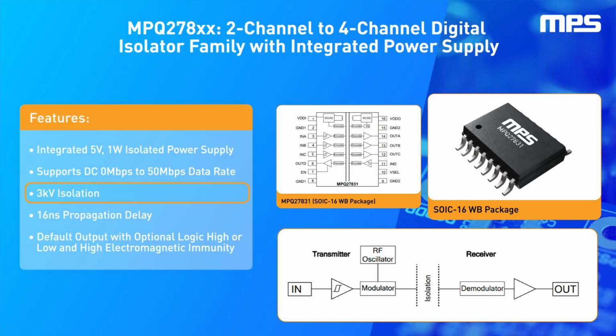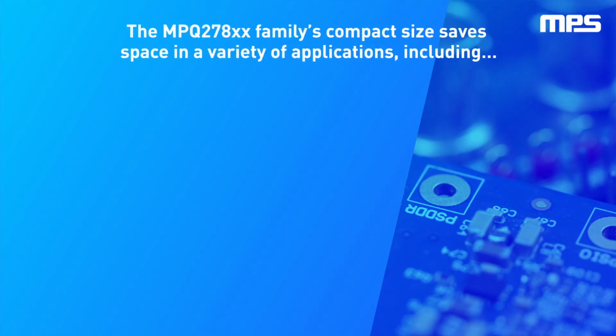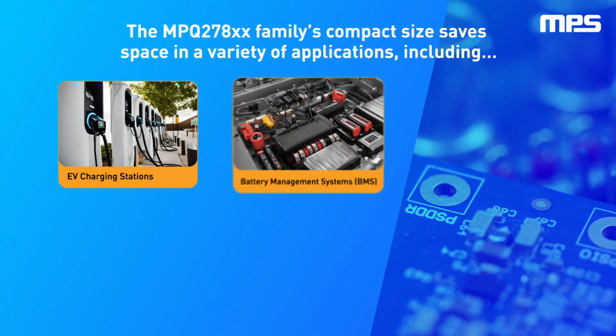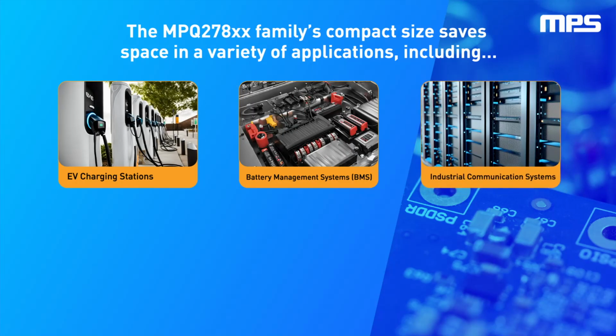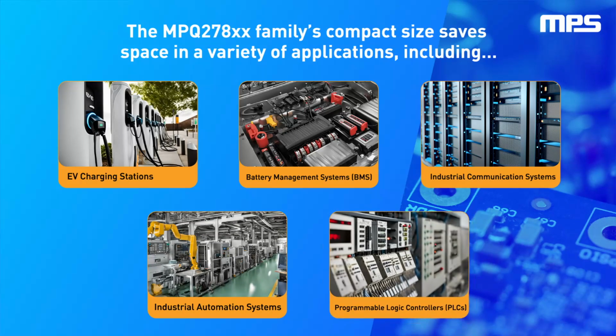The MPQ278xx family of digital isolators with integrated power comes with several output options, from 2 to 4 channels. This family supports data rates up to 50 megabits per second and a 3.3 volt to 5 volt input voltage range. The MPQ278xx family leverages advanced isolation techniques to enable a wide range of applications, such as EV charging stations, battery management systems, industrial communication systems, industrial automation systems, and programmable logic controllers.